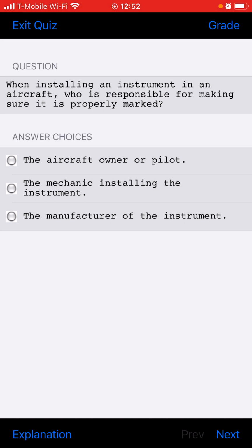What happens to excess pressure in the pneumatic system? A relief valve vents it overboard. What is the function of a restrictor in a pneumatic system? To control the rate of flow of the airflow.